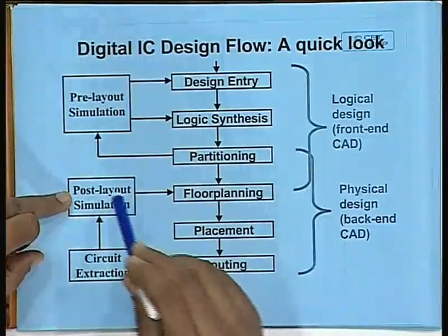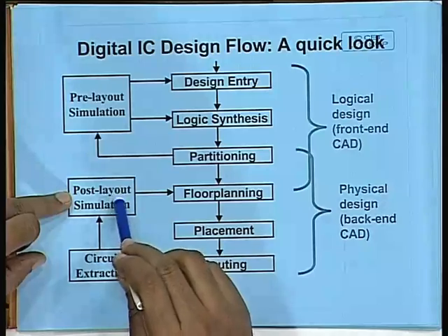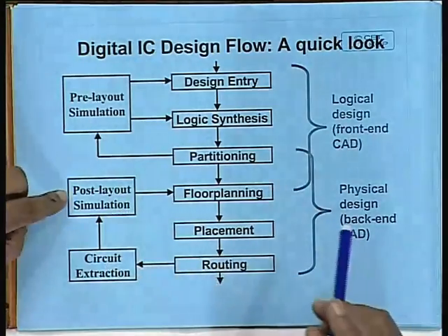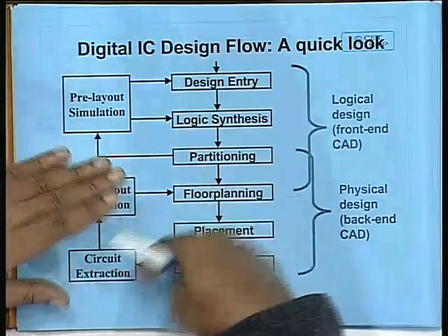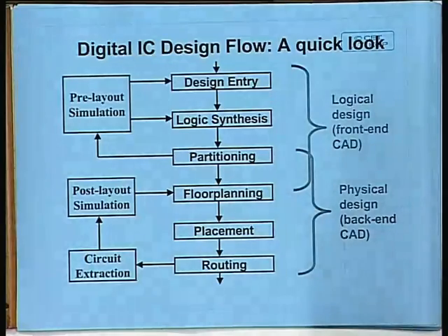But how often do we do this post layout simulation in digital designs? You may not be doing it frequently, but it is a very good practice. Let me give a very good example. You have done a design, you do a simulation at the high level without going through post layout, and you see that your circuit is working at 1 GHz, so you are very happy. But you get your chip fabricated, it comes back, and you see that your circuit is working at 50 MHz only. That is the fact of life. You have ignored capacitances, inductances, noise, crosstalk, everything. But once you do a post layout simulation, you can find out the problem areas of the circuit where the delays are occurring. You can possibly redesign that part so that the bottlenecks are removed.